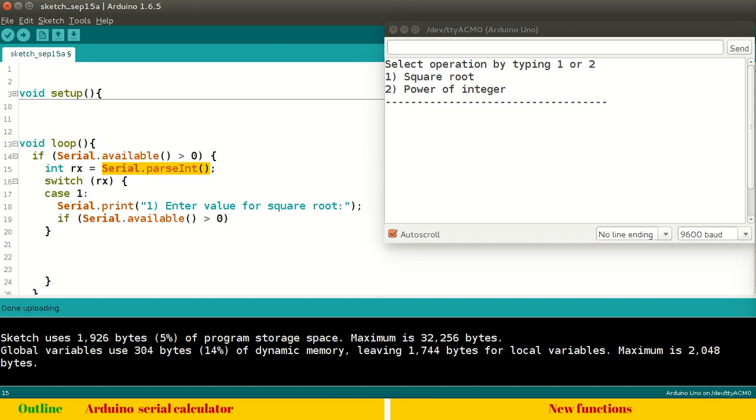that instance. So again, we are using Serial.available, and we are checking whether any serial data is available, and this time we are expecting it will again be a number entered by a user which he wants to find the square root of. Okay, so Serial.available, again let me put curly braces, and int, let's say square, some variable, Serial.parseInt.